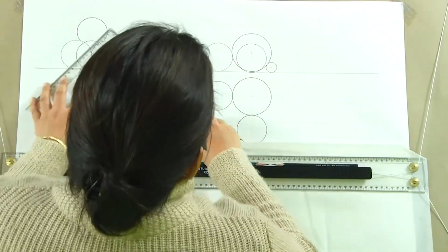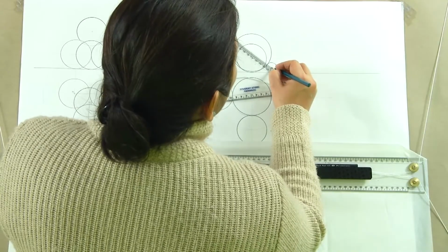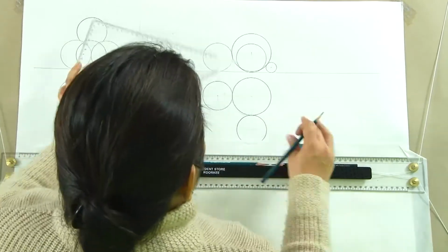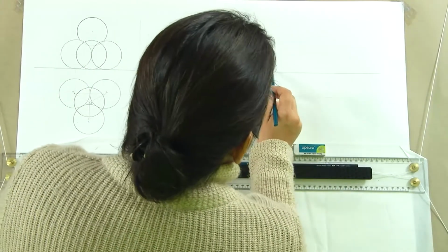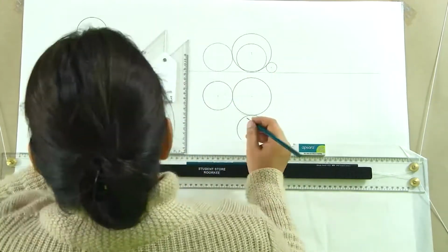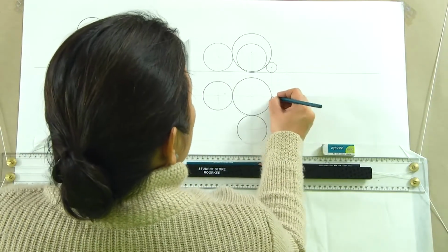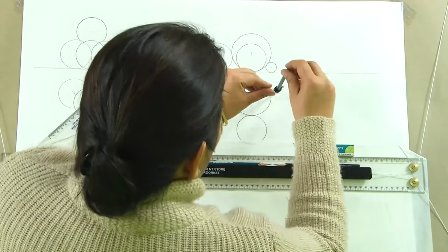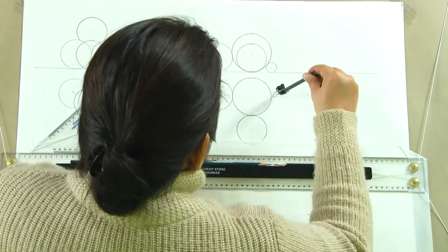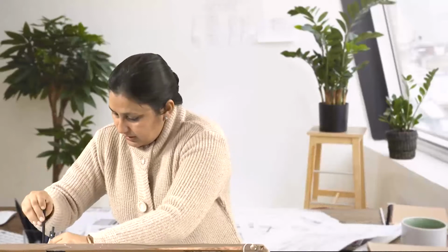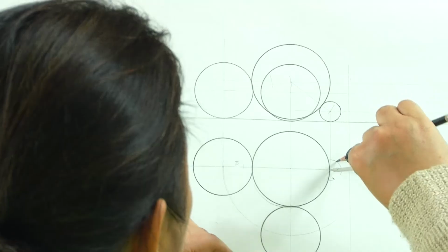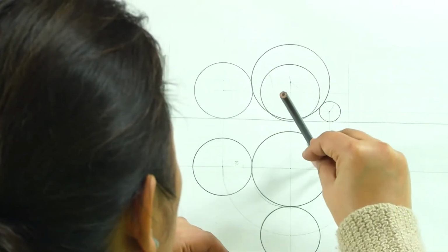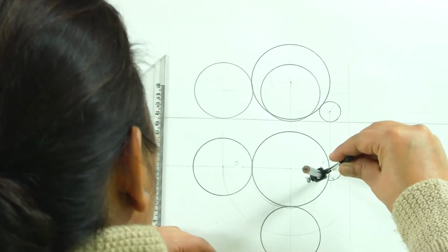So, what we actually have are these straight lines which are joining the centers. Now, this line again is parallel to VP, so we will bring it back onto the same line, and what you actually see is that this is the center of this very small sphere, and keeping this as the center, if I draw the small sphere, we will hardly be seeing this sphere here. It has actually gone inside or beneath the bigger sphere.